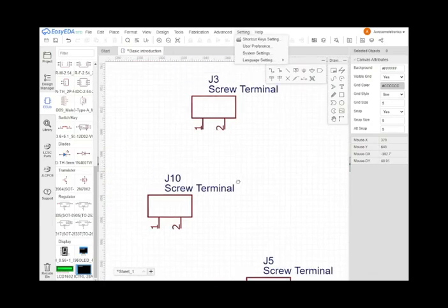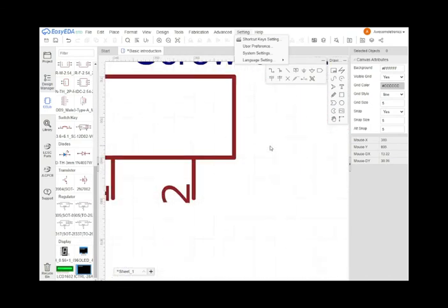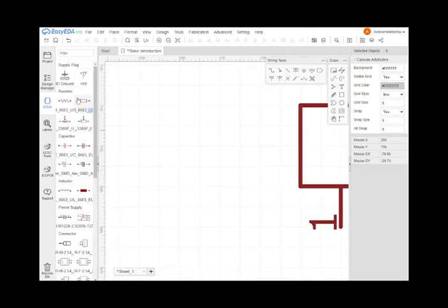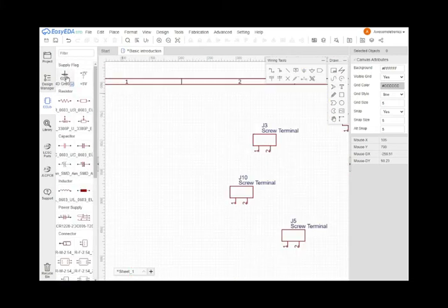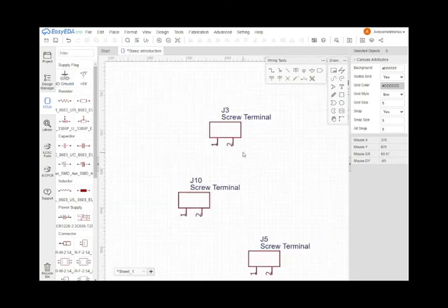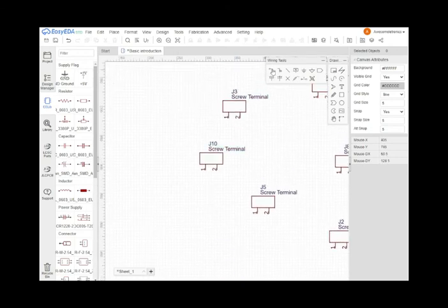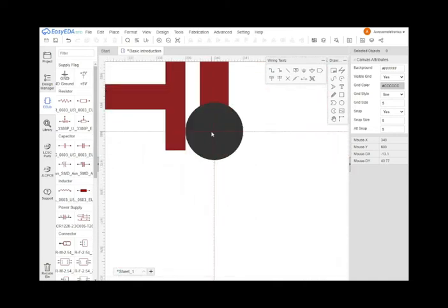So to connect them, we go to the wiring tools. To connect them we use the wires, the net port, and here we have bus and the bus entry and the net flag ground, but I prefer to use this ground actually, because it's labeled, and for beginners it's good. And how we wire is, you just click on the wire, and when some terminal is eligible for wiring, there will be a black dot appearing like this.